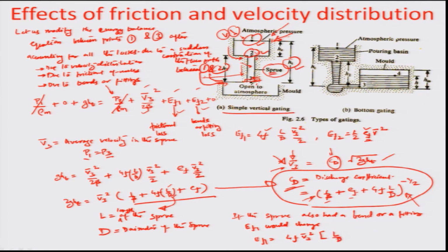So this is the L by D of the wall friction of the smaller cross sectional area, as I had discussed before, and this L by D equivalent, which is a new term which has been added here, is actually a fitting specific term or a bend specific term, and there are many experimental analogies which talk about what this L by D equivalent is going to be. So basically, if supposing there is a bend of a certain dimension, there are data tables available about what would be the L by D equivalent in that particular case.